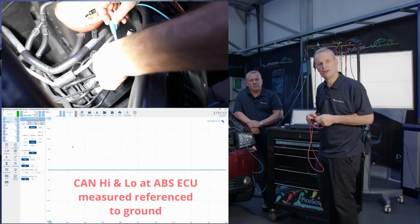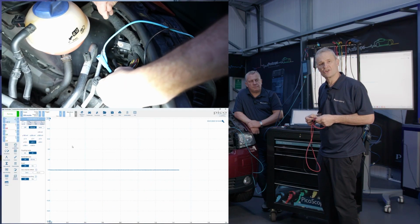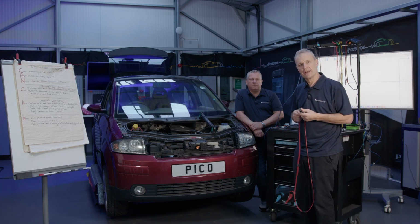So we'll check for voltage here. We can see that they are at 0 volts on the CAN network. We've measured across both sides. Ultimately now we'll move on with an impedance check. So initially we'll use the resistance lead. We're looking for that magic 60 ohms.